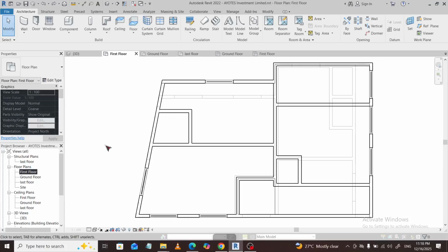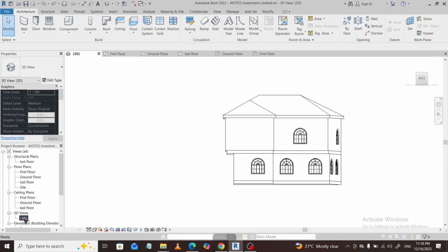In today's video, I'm going to teach you how to measure accurately in Revit's 3D view. First, make sure you're in a 3D environment. Open your 3D view by activating the default 3D view or any custom 3D view you've created. The key here is that the view must be active. Revit only shows measurement tools when a view is selected and ready. If you don't see the tools later on, click inside the 3D view window to activate it, then continue.